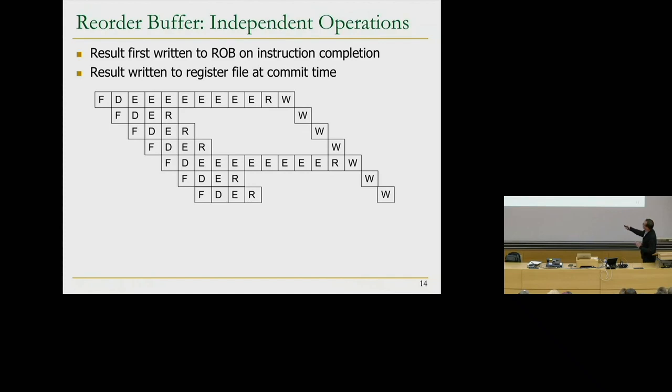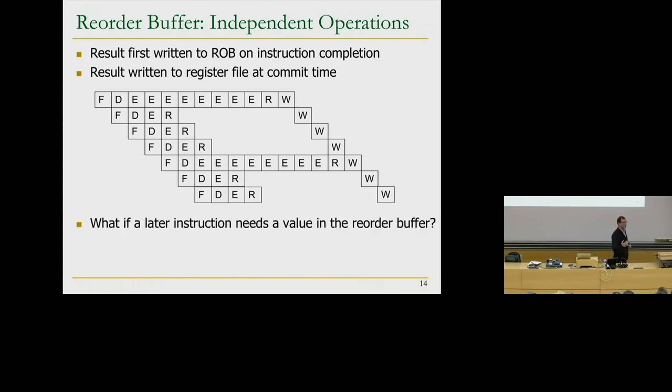This way you don't need to lengthen the execution of this instruction. You basically write the result into the reorder buffer. As you can see, these are all adds, and this multiply takes 8 cycles. So the key thing over here is the writes are moved over here. The register file updates are moved over here so that they're in sequential order. So now the programmer doesn't go crazy. Okay.